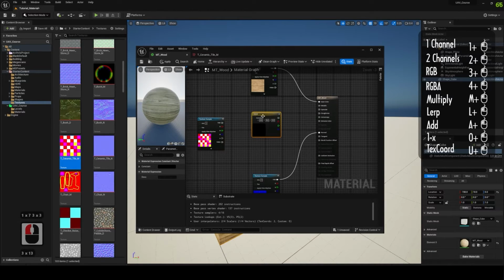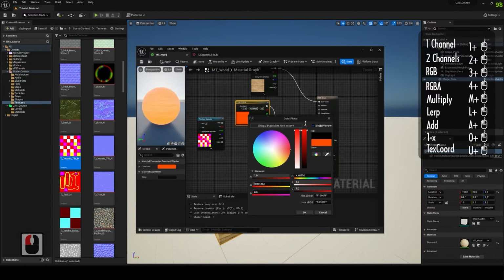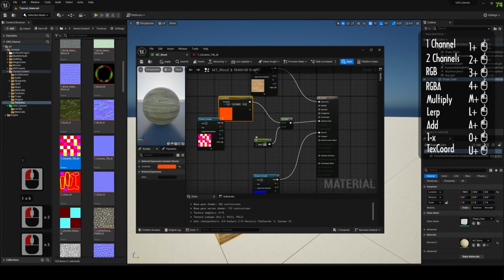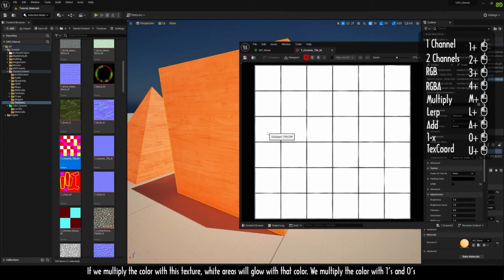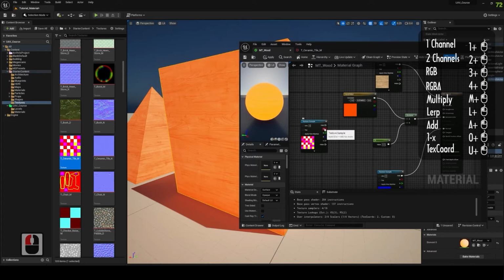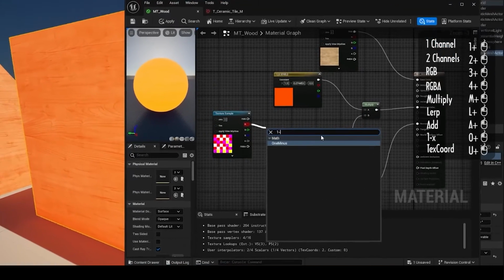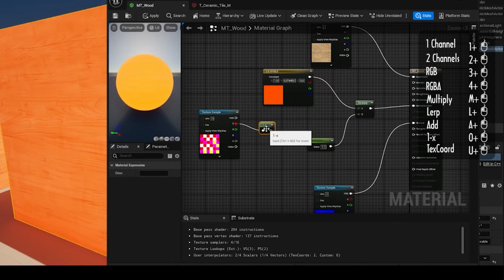Now, let's try to make our joints emit light using the red channel. First, let's create our emissive input as we saw before. If we inspect our red channel, we will see that the gaps between the joints are black. However, the color values in the area we want to change should always be closer to 1, meaning they should be white. We can achieve this by inverting the node we extract from our red channel with the 1- command. This way, we can turn the black areas into white.